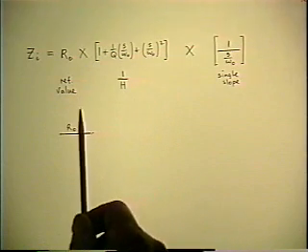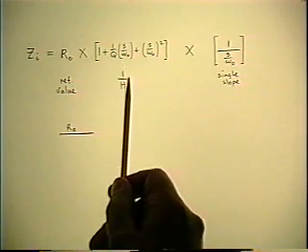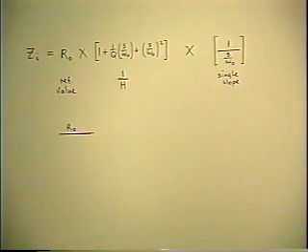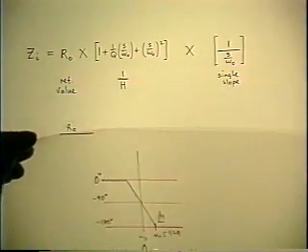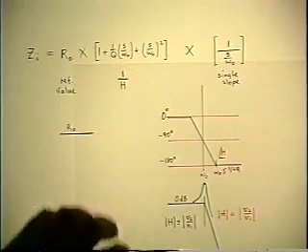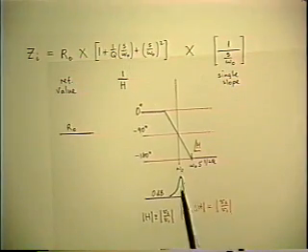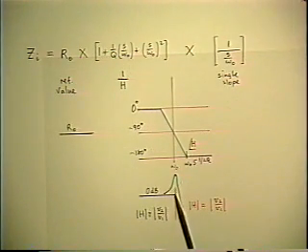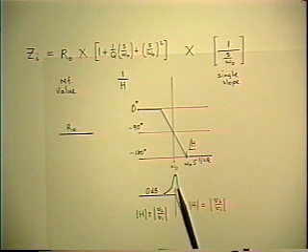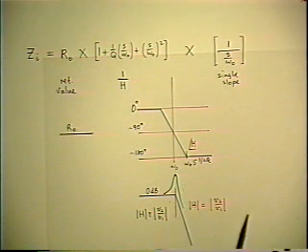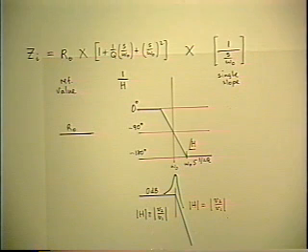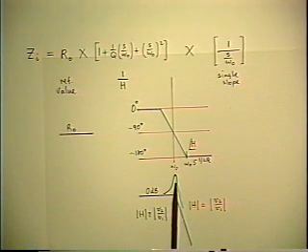Okay, so the next factor is the reciprocal of the voltage transfer function. Well, here's the H that we already set up. Peak response, I'm sketching the case for high Q. I could equally well sketch the case for low Q with the two real roots, but I'm going to leave that for you to do as an exercise. So I'm sketching the high Q case.